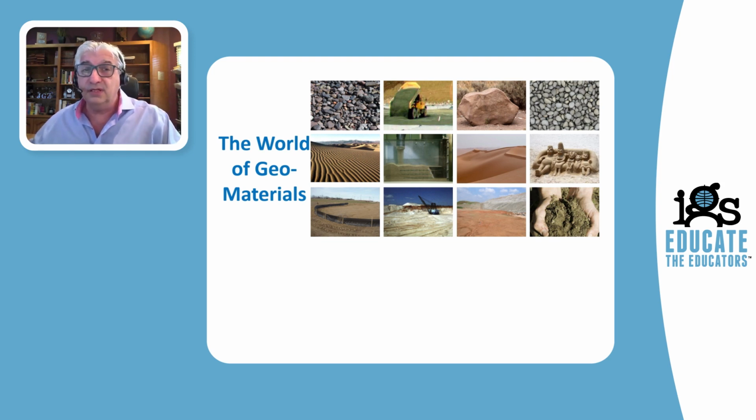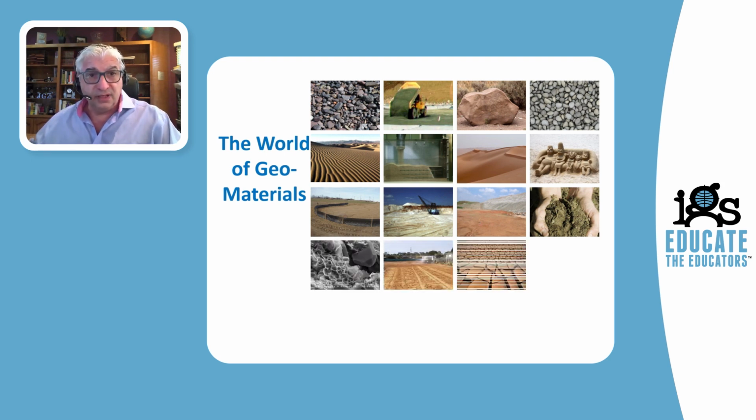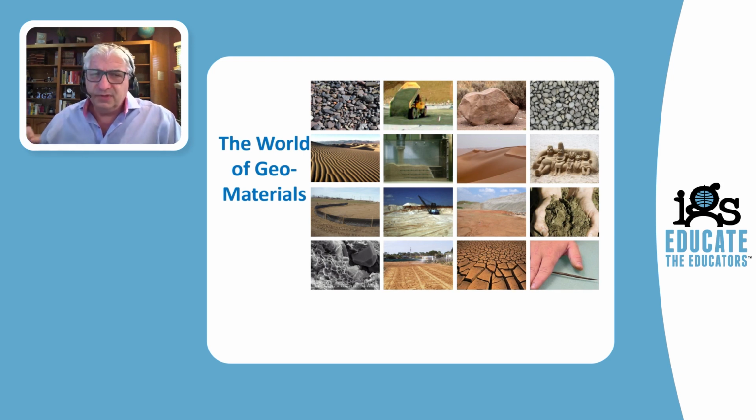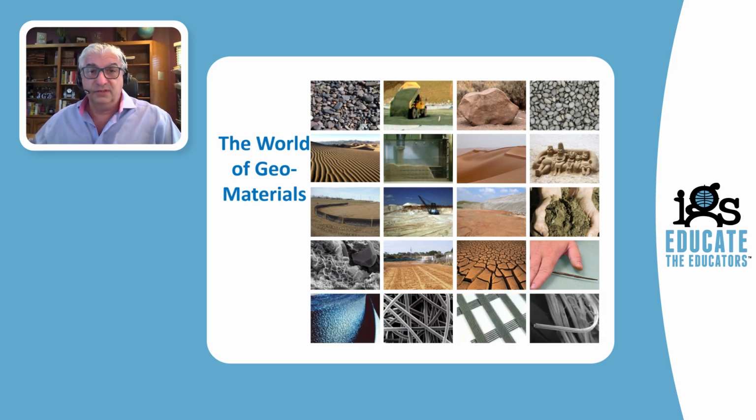So these are particularly good for agricultural purposes. And then we get into the clays. By particle size definition, they are the particles with sizes below 2 micrometers. But the most important aspect that governs their properties is that most clay particles are also clay minerals. The mineralogy of the clays is what governs the hydraulic and mechanical properties of clays. Now, we have a new type of geomaterials, the ones that we're going to cover in this class, which are